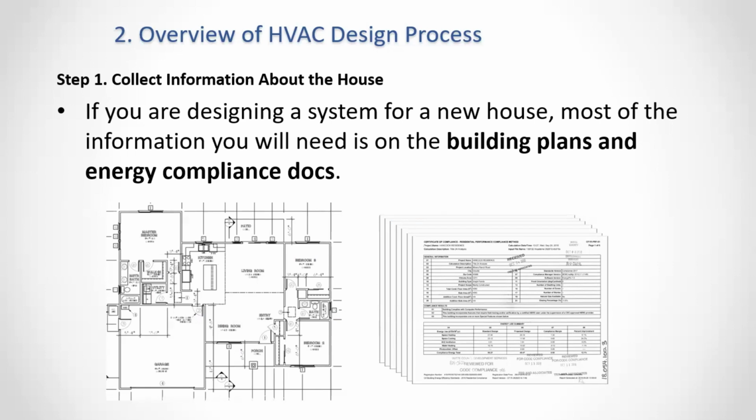I do designs all over the country, and there are parts of the country where I'll ask, what kind of windows are you putting in? They'll say, I don't know. As soon as we're ready to put the windows in, we'll go buy some. They have no clue, and the energy codes are basically non-existent. They don't know what they're putting in the house until the very last second. So how do you do a load calc on that? You kind of have to assume worst case, but then you don't want to oversize your equipment either, so it gets pretty tricky. We're fortunate in California that we have very detailed load calculations, or sorry, energy calculations. Next slide, please.